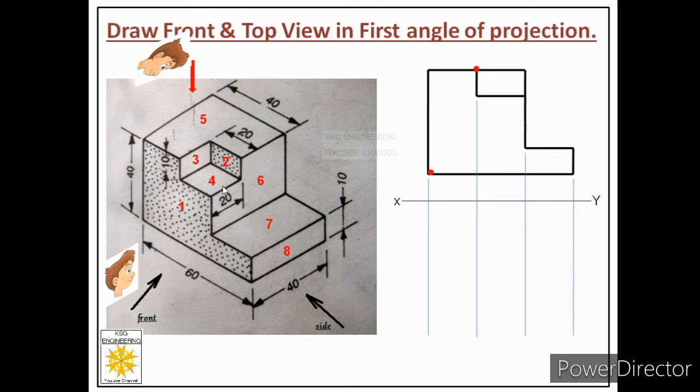And apart from these three faces, there are no other faces parallel to HP. Now let us see how many are inclined to HP. And you will find that there is no face inclined to HP. It means we have concluded that we have to draw only these three faces with their proper dimension and location in order to get the top view of this object.